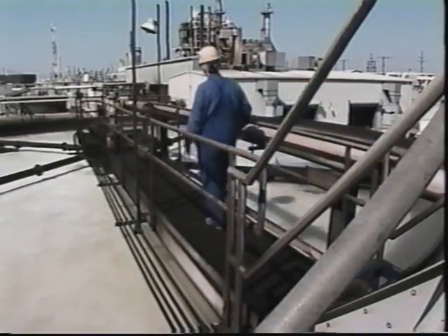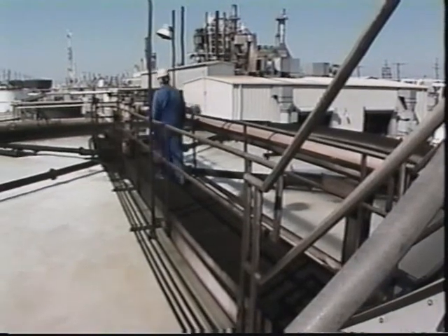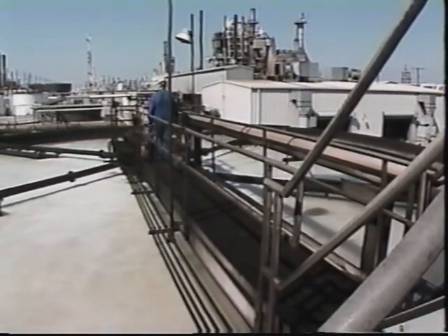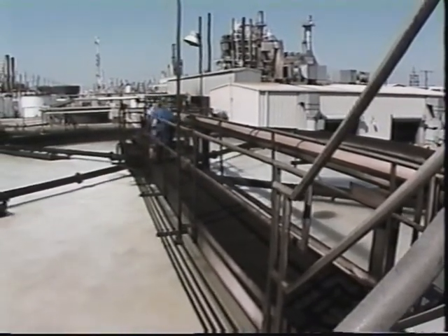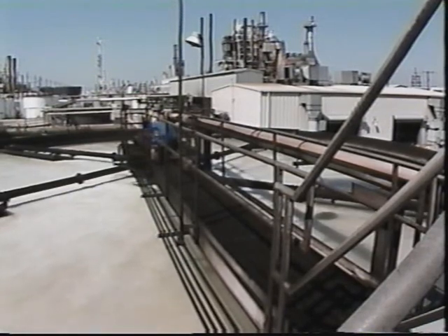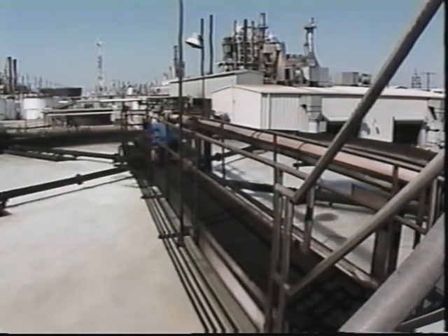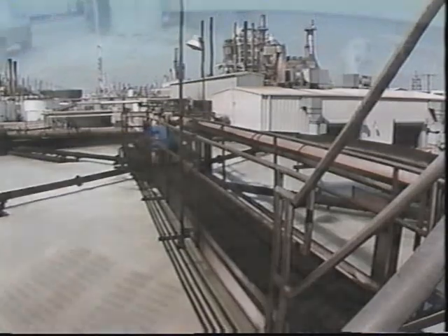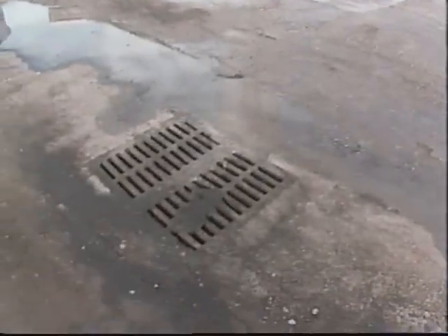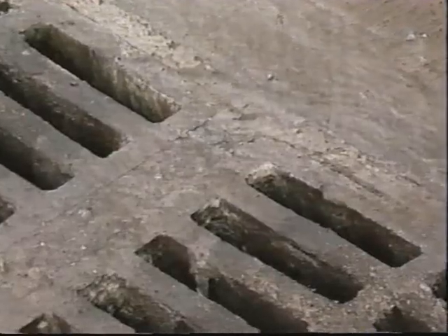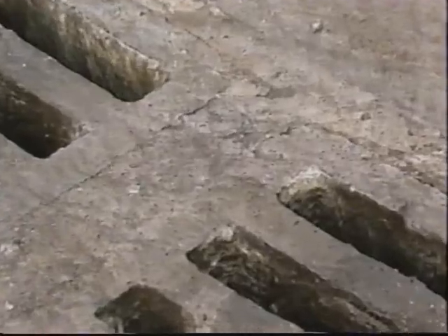The operator also sees if the clarifier itself is working properly. If it's not, the sludge level could build up. But he finds it to be functioning okay, so the problem must be elsewhere. The high level could be caused by introducing water with a high solids content into the treatment system.